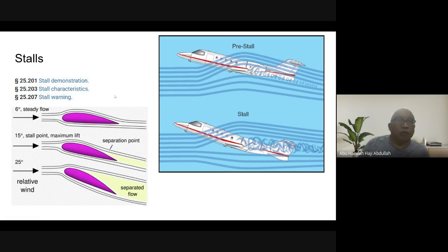So, stall warning. And we ask why the Eagle has two wings, because the idea is we don't want to stall the aircraft. It is impossible not to stall the aircraft. However, with the biplane wing that we have on the Eagle, the first wing stalls, and then the second wing will not stall. Then we correct it by nosing down, and recover the stall from the first wing. So that's why you can say the Eagle is never able to stall because of that situation.